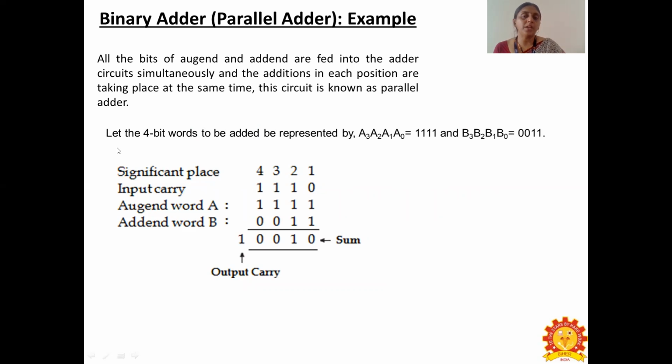When we add A1 and B1, along with which we add the carry 1 also, we add 3 bits and get the sum result as 1 and again carry as 1. The carry value 1 is added with the A2 and B2 values, where the resulting sum value is 0 and the carry value is 1 again.